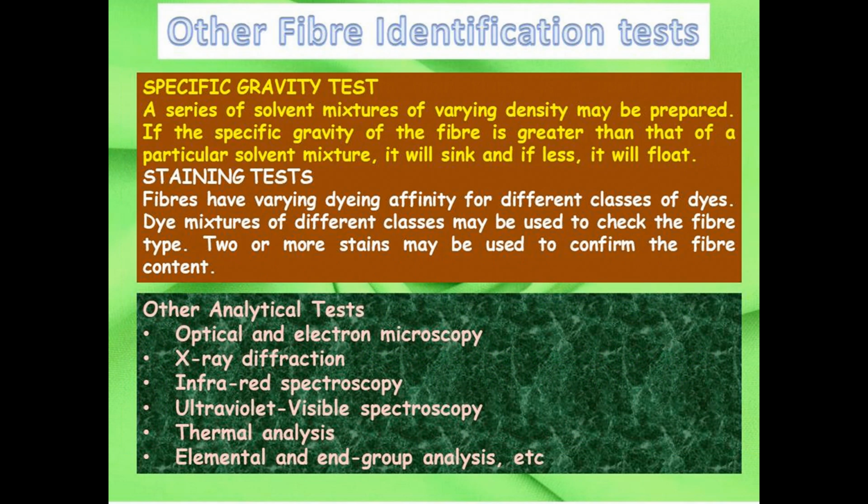Other fiber identification tests. Specific gravity test. A series of solvent mixtures of varying density may be prepared. If the specific gravity of fiber is greater than that of a particular solvent mixture, it will sink, and if less, it will float. Staining test.